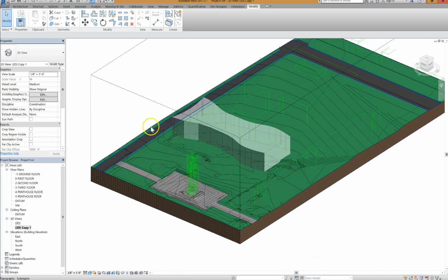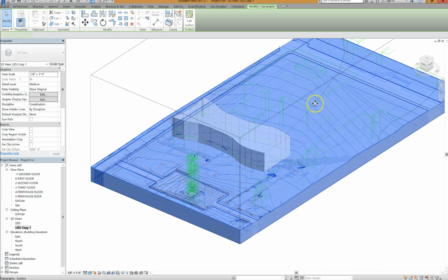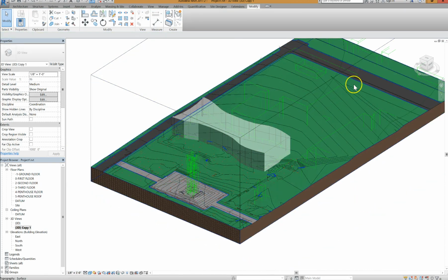There are very specific ways to bring in other geometry. If you have these modeled in another piece of software, you can bring them into Revit, but you would want to bring them in as a family. There's another video on this YouTube channel that shows exactly how to bring in stuff from Rhino or anything like that. If you just bring in the geometry the way we did it from AutoCAD here, see how I can't click on any of these surfaces. I can't make new walls off of them. So that's something else that you can do.